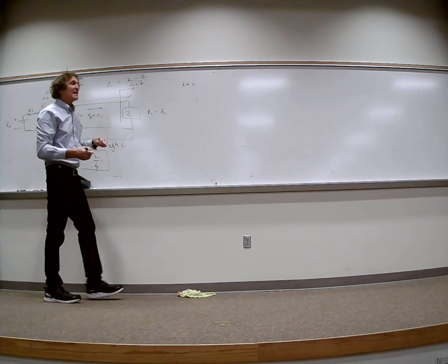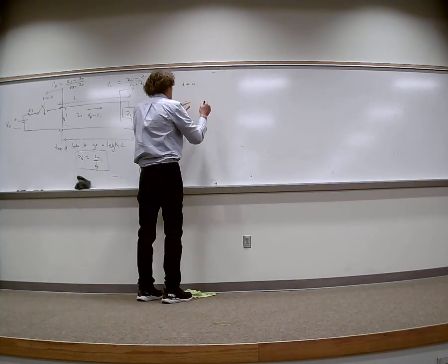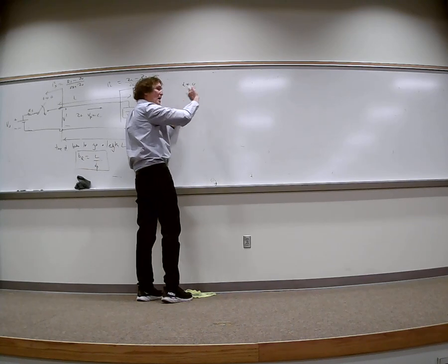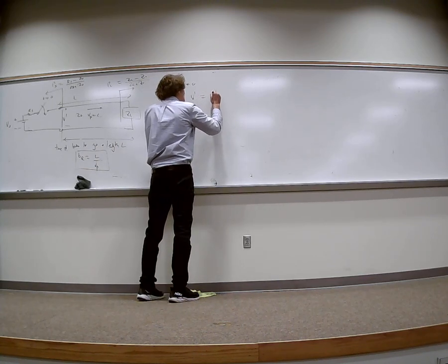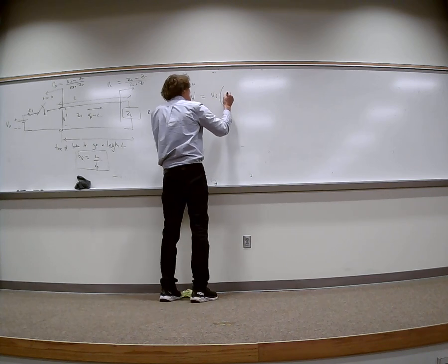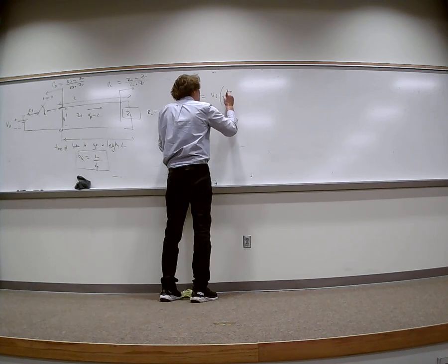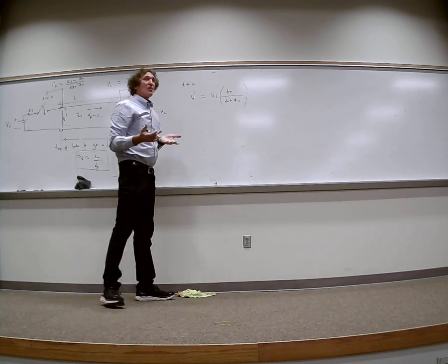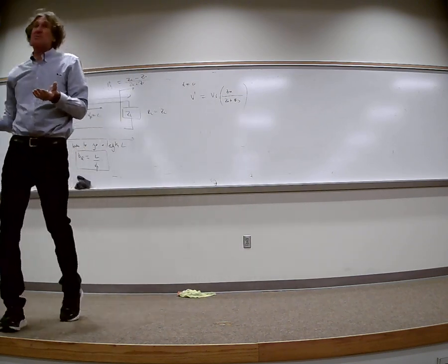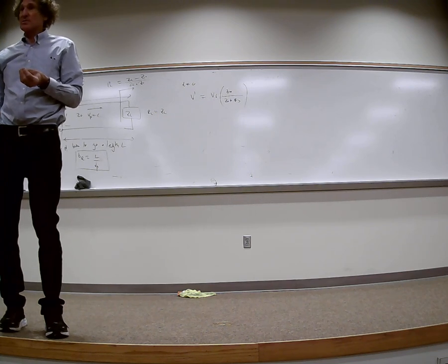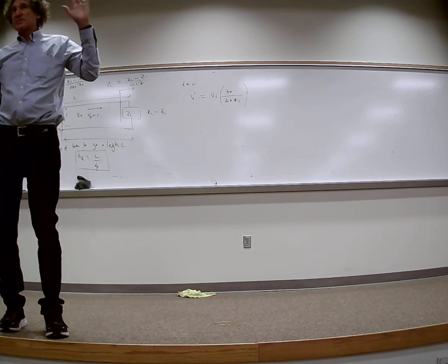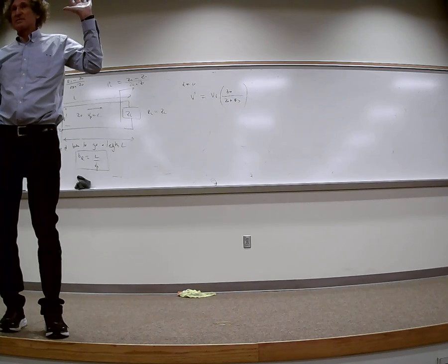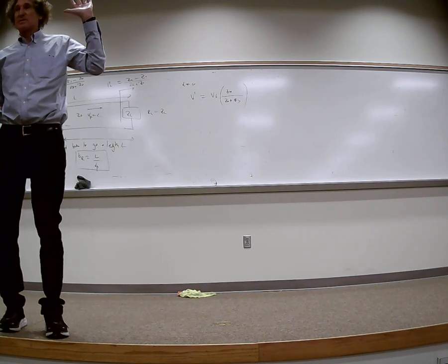All right, so at t equals 0, that V prime, that's going to be the actual magnitude of the wave that's going to go down there, will be Vs times Z naught over Z naught plus RS. So if there was no RS, effectively it would just be Vs. Do y'all follow me? There's no source resistance. How many understand this right? I don't mean to go so fast. I'm trying to just get the basics out of the way that you can see easily.